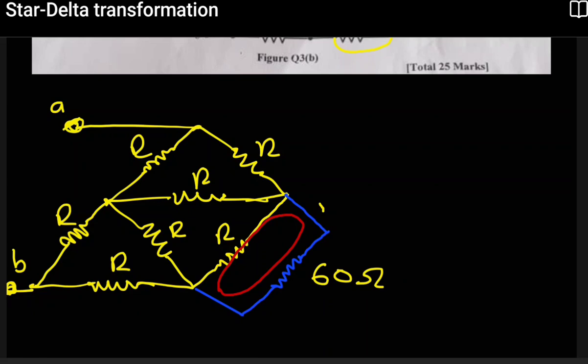Picture all the other connections. If you look at, let me say, these two resistors here, are they in parallel to each other or are they in series? First of all, you can clearly tell that they're not in series. But maybe, as I'm claiming here, are these two in parallel? Well, let's start. If we want to see if they're in parallel, then we should only have two junctions or two nodes. So when you start from this side, you find the first node at B here. You continue, you find the second resistor, fine. But when you look at this, you found another node. And when you continue, you find another node. So these two are not in parallel to each other.